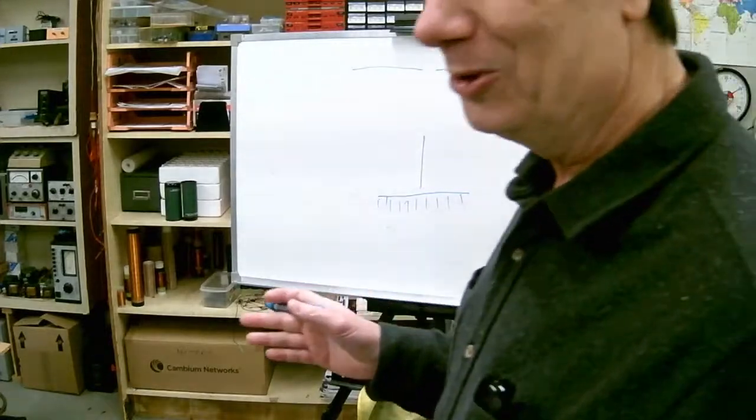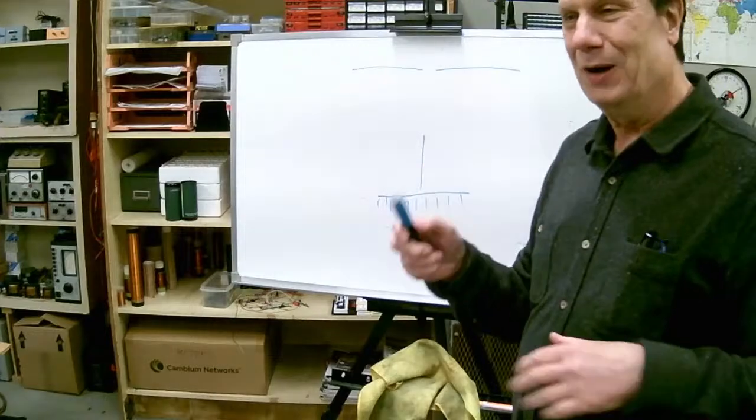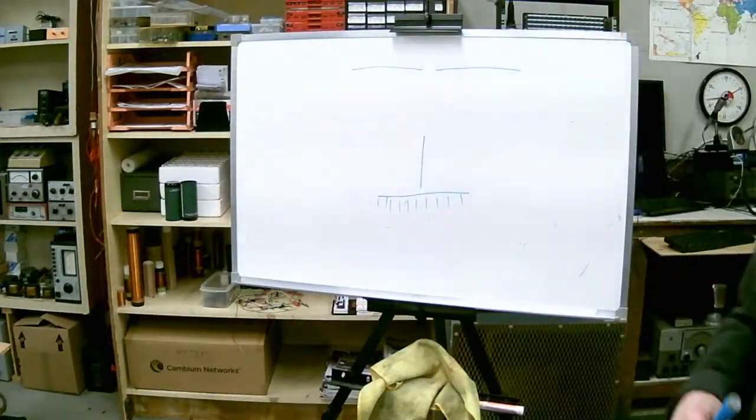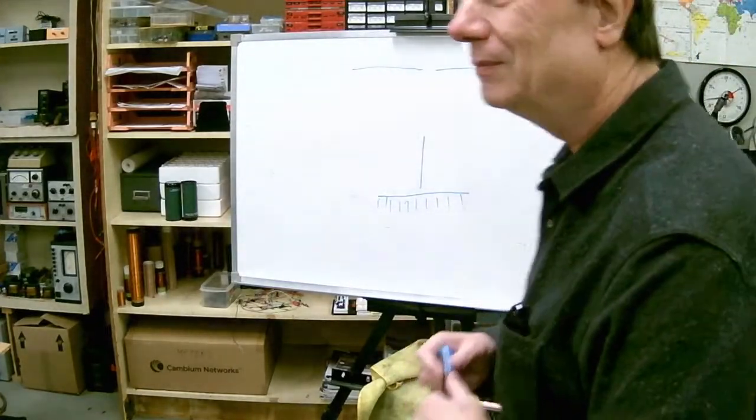Now underneath broadcast stations, it usually is pretty much paved with copper. You have 120 radials of copper wire underneath every tower. It goes out a quarter wavelength. So there's a lot of copper under broadcasting stuff like that.